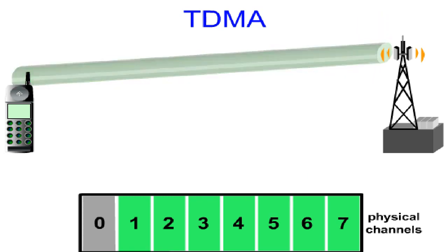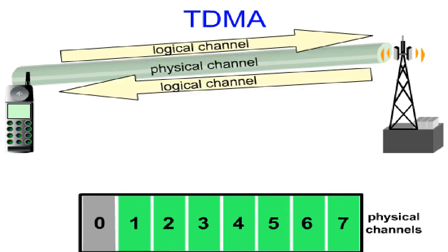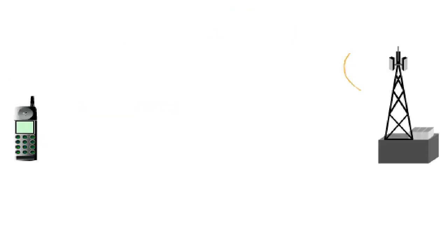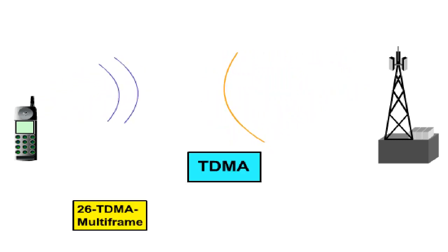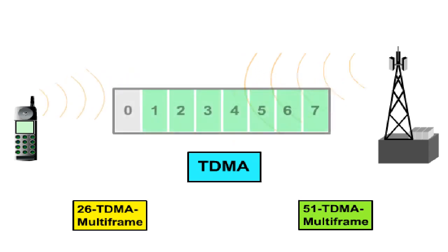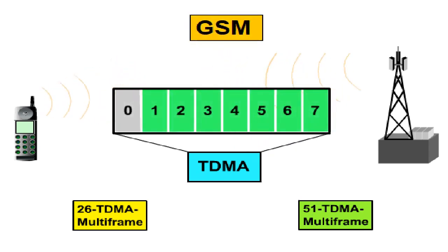Thus, the physical channels provide the resources used to transmit specific types of information. The types of information and the functions define the logical channels. The logical channels differ according to the function they fulfill in data transmission. To organize the radio transmission, various frame types consisting of numbered time slots are specified in GSM. The numbered time slots are continuously numbered off by the mobile station.